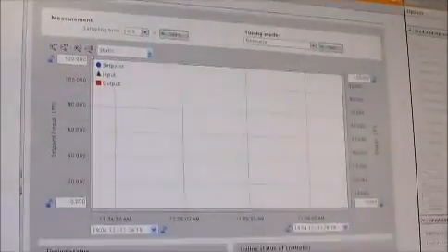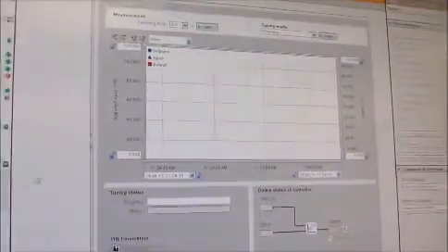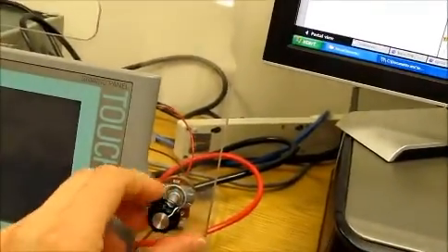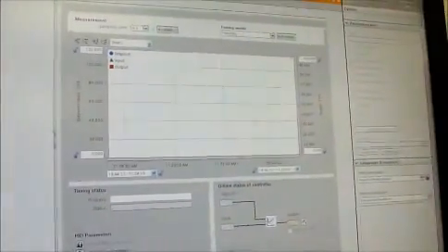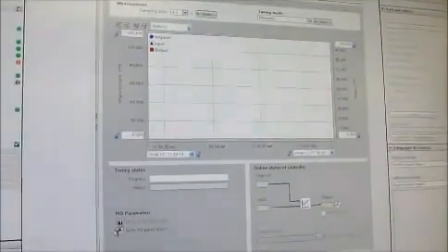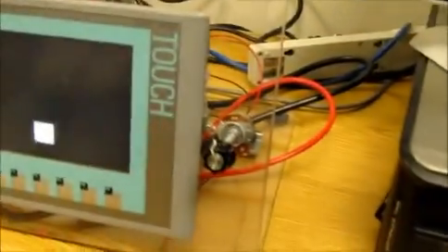When you double click that, you're going to get this window, and that's basically where you do your tuning of the PID block. You're going to have to turn your set point to, normally you want it to open all the way, but our particular valve doesn't actually reach the full 90% or 100%, so we're just going to set it somewhere towards the middle.